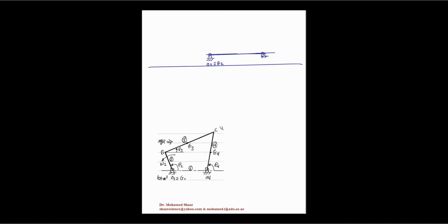Then you're just gonna measure the angle theta2. Theta2 angle is already given, which is this angle down there. It is already given to us as 135. So you're gonna use the protractor and, fixing from this point, you're just gonna measure an angle in this direction with 135. Then you're gonna mark a point on the top somewhere here. Then you're gonna connect this center point to this point to draw a very light line in the beginning. We can use even a different color here for this line. You're just gonna draw a very light line that is barely seen.